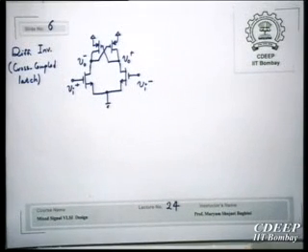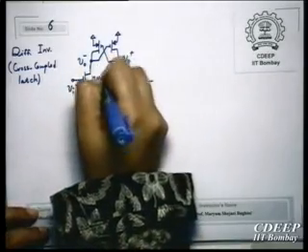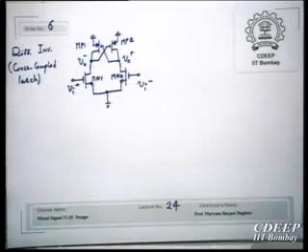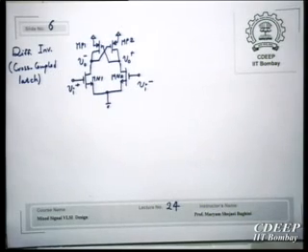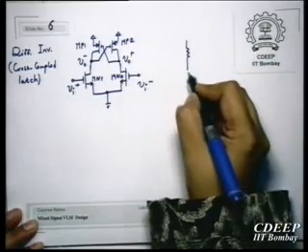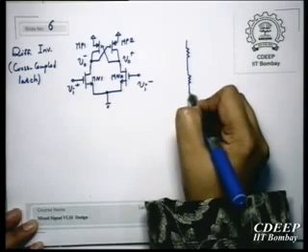Differential inverter. So MM1, MM2, MP2, MP1. This circuit essentially has positive feedback, right? Because of this cross-coupled latch. What is the effective equivalent circuit of this? If you look at the half circuit model, small signal analysis.